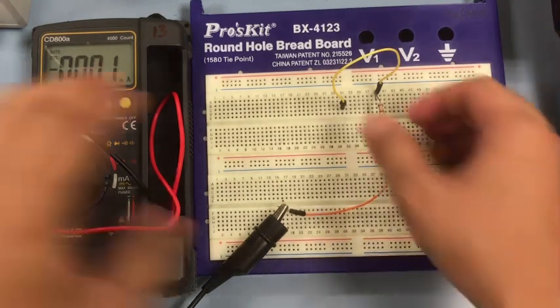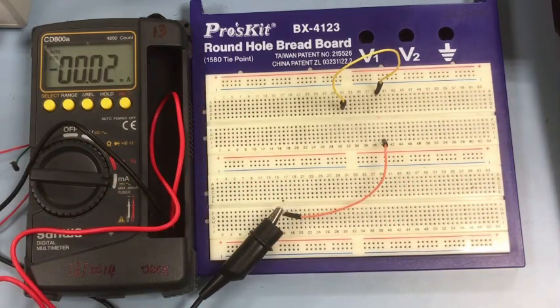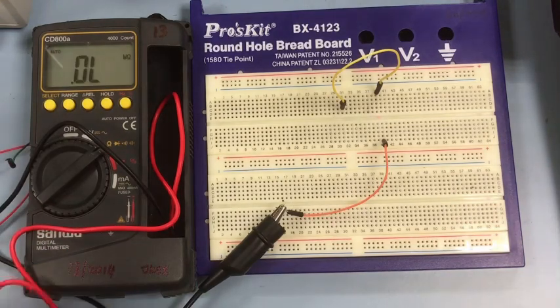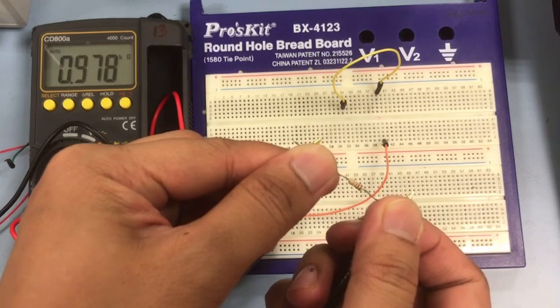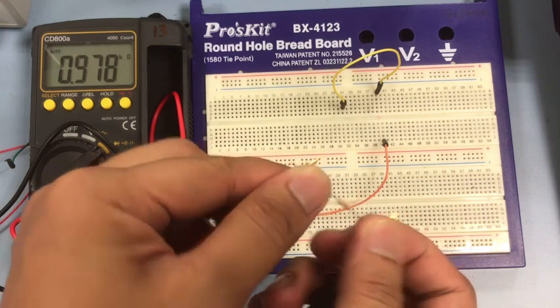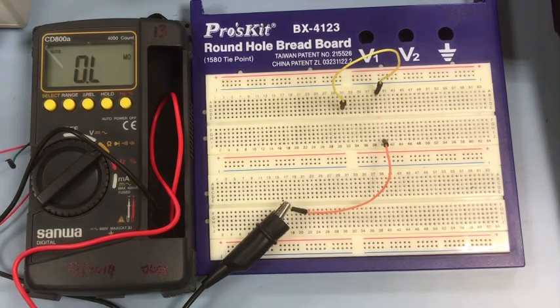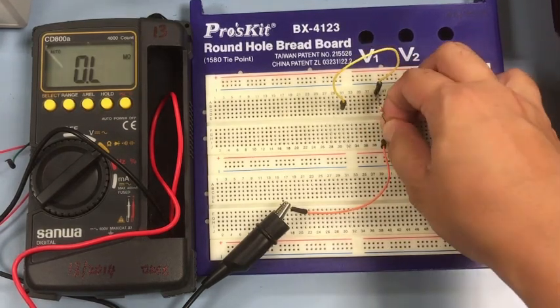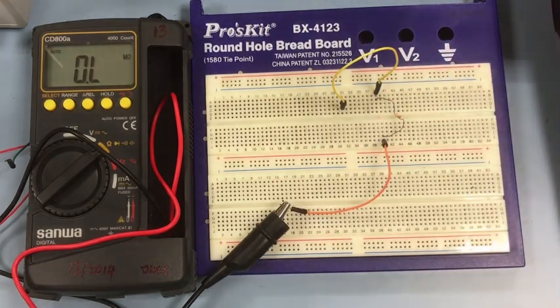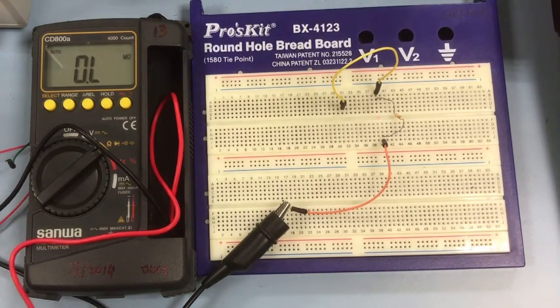Okay, turn off. Then we go to the last one, which is 1K. Make sure you measure first, because we don't know what is the actual value in this resistor. Is it 1K or below? So you can see here the value is 0.978, so 978 ohm. So in the theoretical part later, you need to calculate the theoretical based on the actual value of the resistor. So this is 1 kilo ohm, 978 ohm.